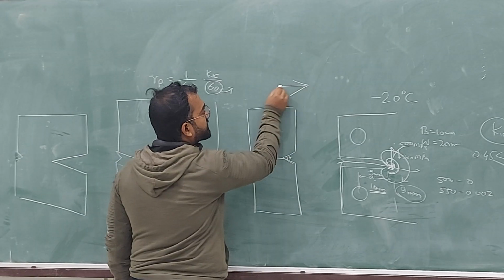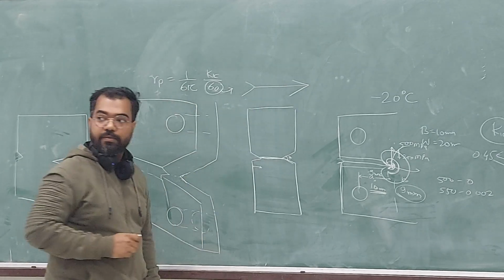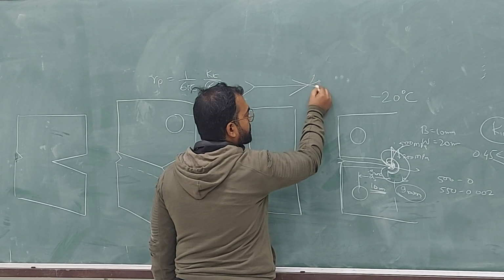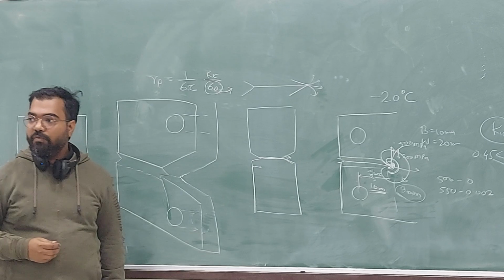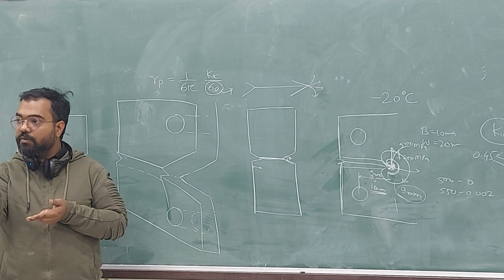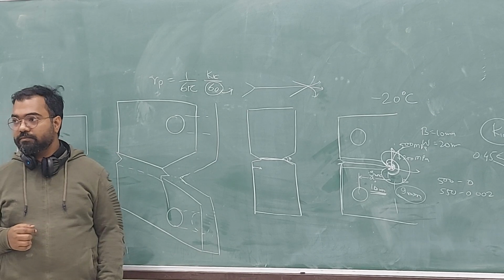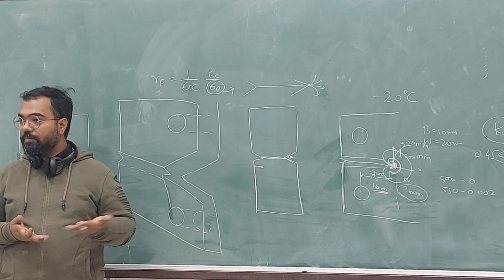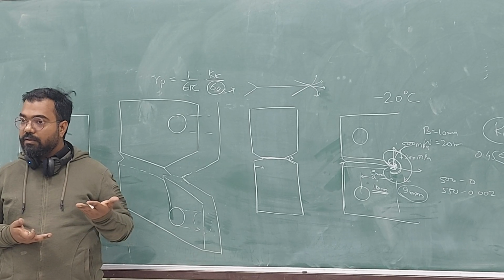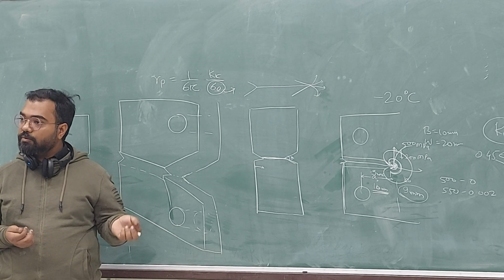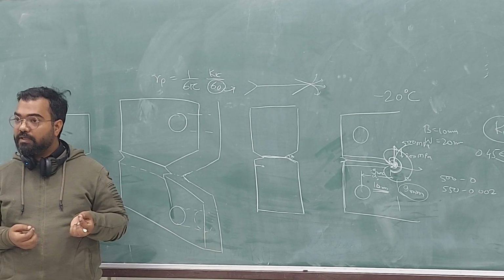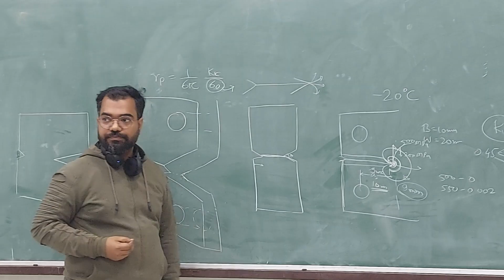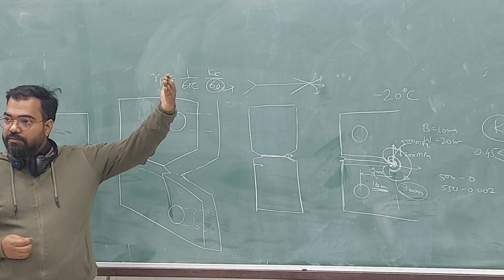In 3 dimensions it will look like this. So this is a line, right? When a crack initiates, it can go in any direction. Why would it be perpendicular to the force applied? Because of the stress situation. It has a higher probability of being perpendicular to the applied force in mode 1. But there might be scenarios where you have some inclusion or manufacturing defect, because of which you have created a high stress region in some other direction, so the crack might go in another direction.